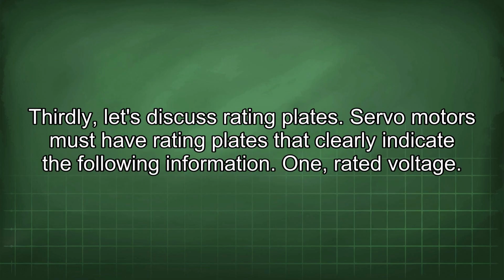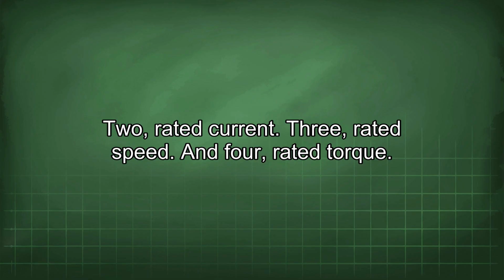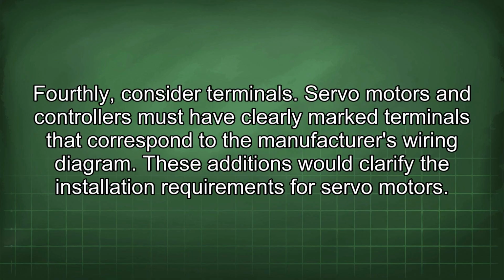Thirdly, let's discuss rating plates. Servo motors must have rating plates that clearly indicate the following information: 1. Rated voltage, 2. Rated current, 3. Rated speed, and 4. Rated torque. Fourthly, consider terminals. Servo motors and controllers must have clearly marked terminals that correspond to the manufacturer's wiring diagram.